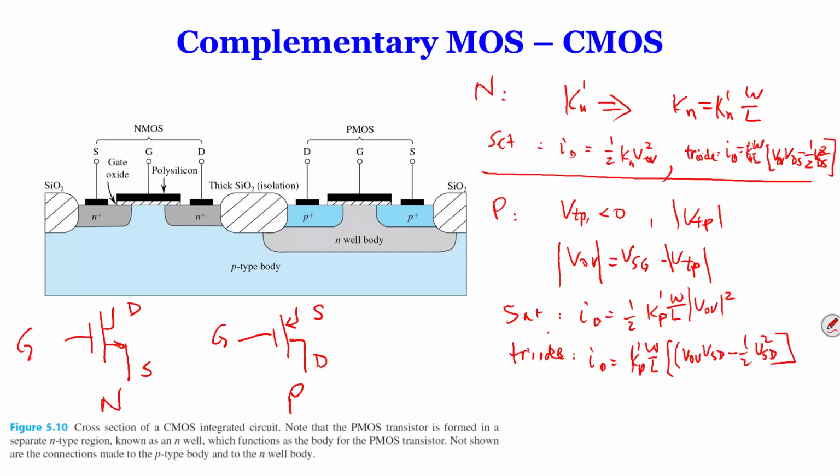So there are a lot of similarities, but there are also a lot of differences. But when you do PMOS, there's one thing, of course, we're going to have examples in the future. If you memorize that VSD, if you use everything absolute value for PMOS, it's going to be identical as NMOS. So one of the questions you're asking often is, if that's the case, why would you need PMOS?